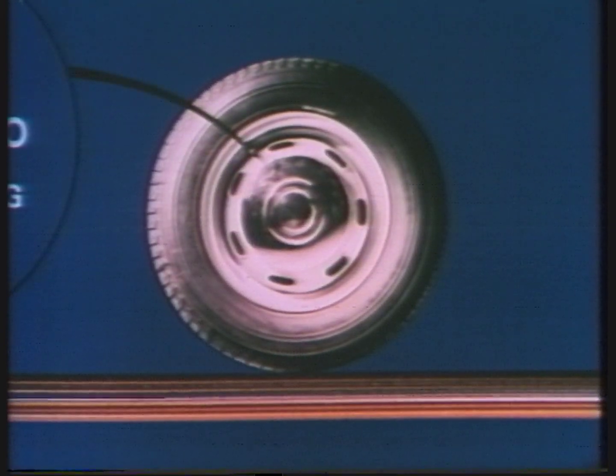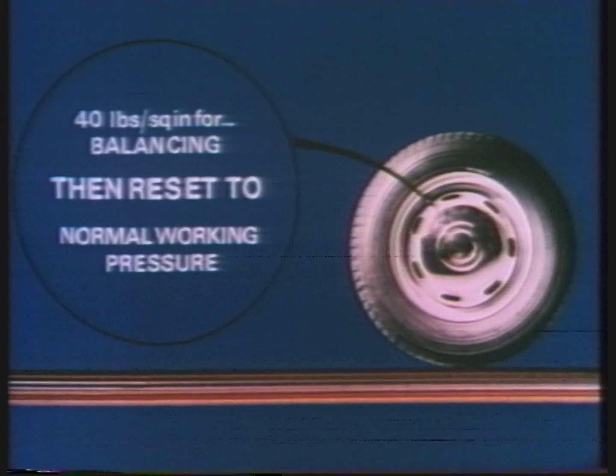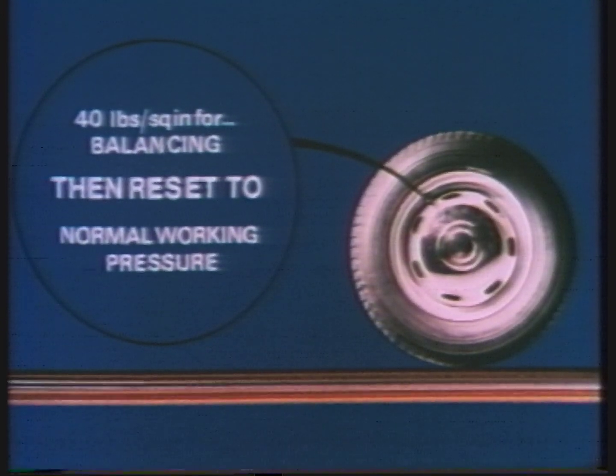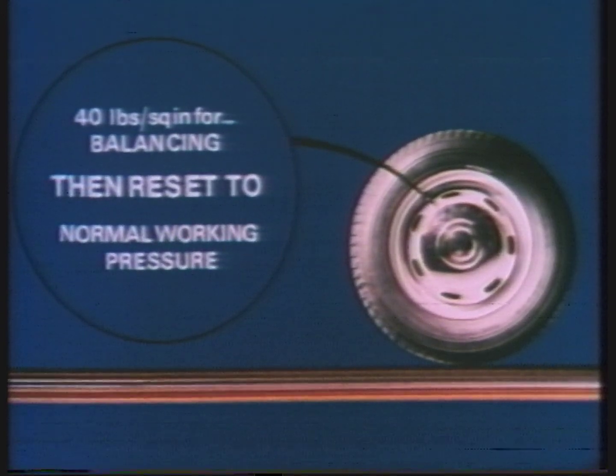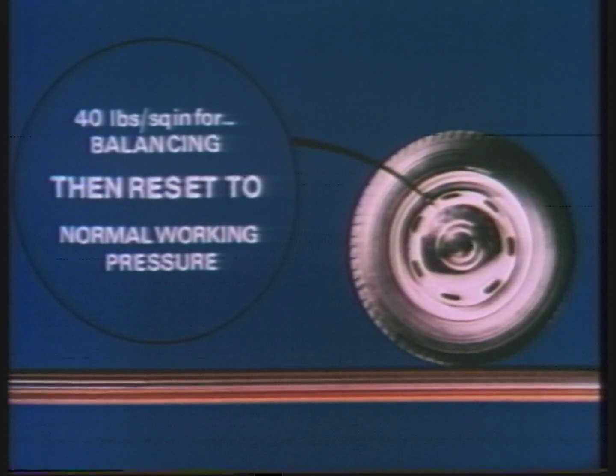In connection with this last point, inflation to 40 pounds per square inch helps to maintain roundness. But remember to reduce to normal working pressures afterwards. You don't want to frighten or annoy your customer. Besides, there's the question of safety and legal liability.